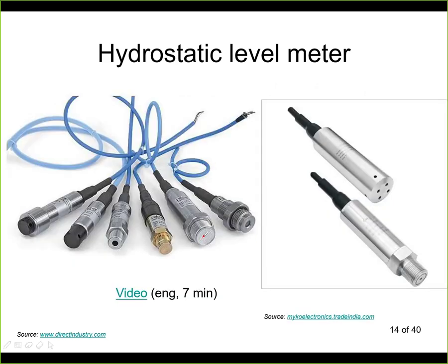A few more examples here so that we see the sensors from a different angle. Again, all those are basically pressure sensors. So in all cases there is a diaphragm. Here we can see the diaphragm over there, here and here. In here the diaphragm is actually hidden, and the liquid enters only through this opening that we have here. You can see different versions, opening from the sides, opening in the axis, and so on. We can see here the same stainless steel cylinder.